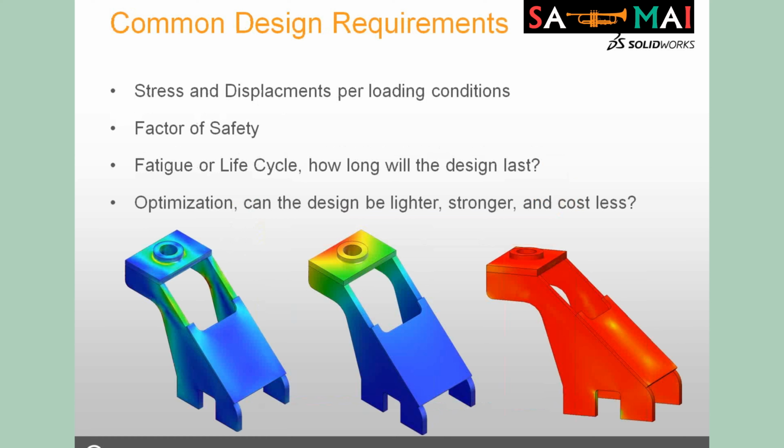Some of the common design requirements across all industries are, number one, stress and displacements per the loading conditions. If you look at that press at the bottom, how much stress develops when the load is applied? What is the displacement that we're seeing out of this? Is it a quarter of an inch? Is it an eighth of an inch?